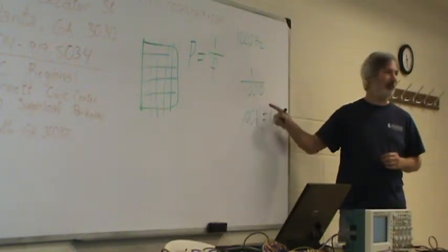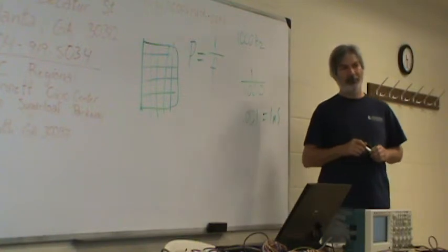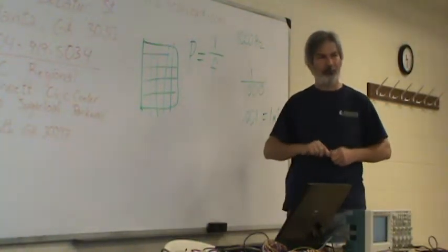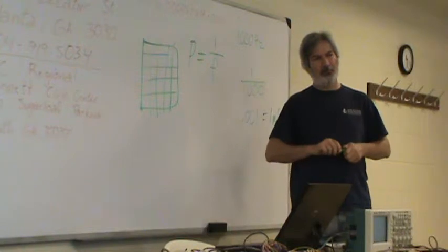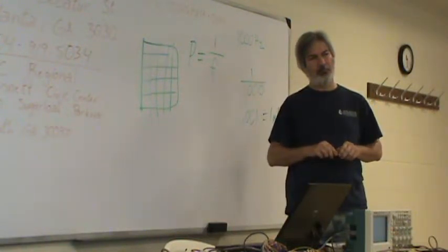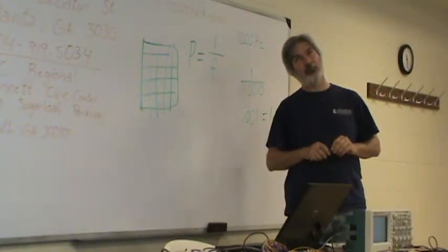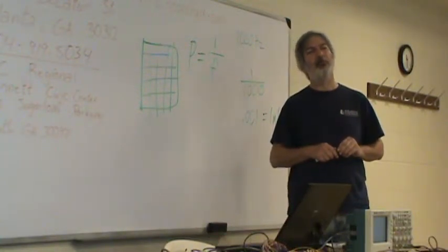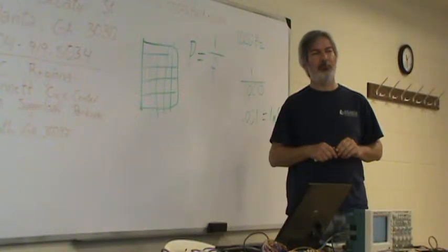this won't make sense. I think a real easy way to do all that is just set the sweep up. If you've got a totally unknown signal, crank your sweep up as fast as it goes, and you'll get just some line. Keep backing off until it starts showing the signal. If you do it the other way around, starting really, really slow, that's where you're going to get aliasing. As you start stepping up, you get aliasing first, because the sweep time is too slow and your sample rate is too long between samples. And as you go up, you'll eventually see something, but it may be wrong, because it may be an alias.